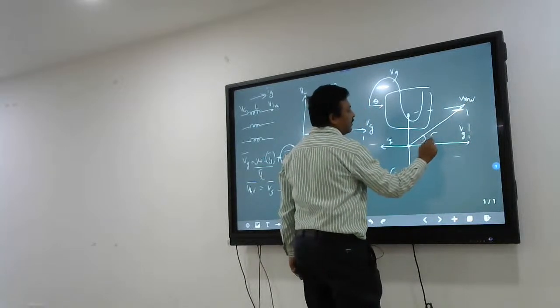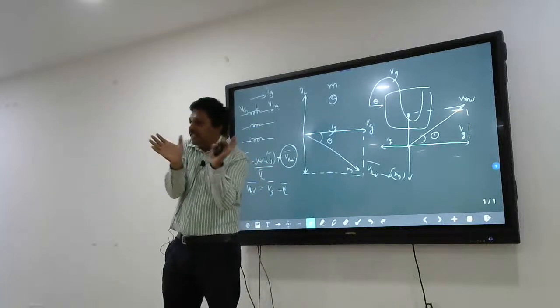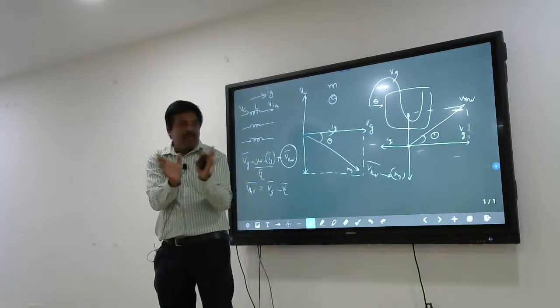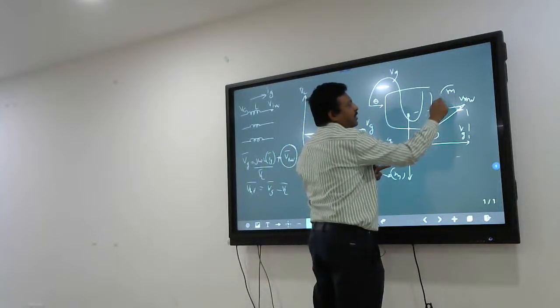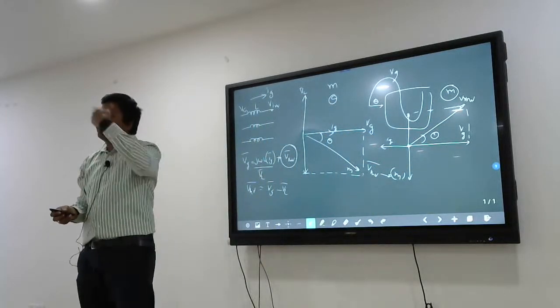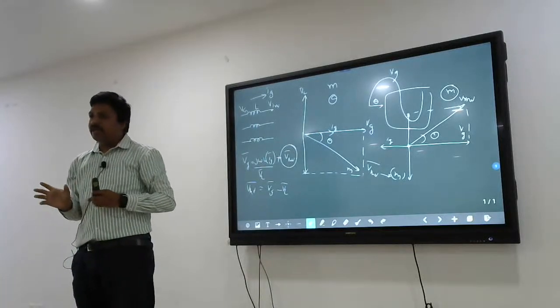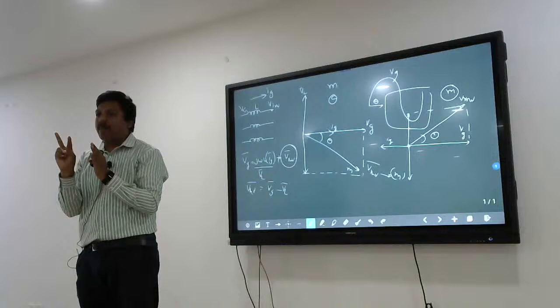So this phase shift is positive. That means you create a leading phase shift of the PWM with this modulation index. This is decided by the modulation index. Then it helps us inject power into the grid. Are you clear what I am saying? So in the case of an inverter, there are two variable parameters.